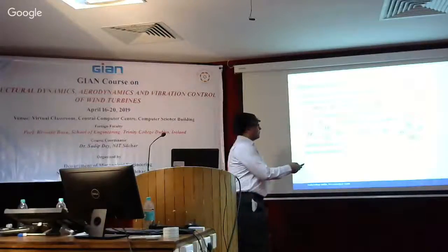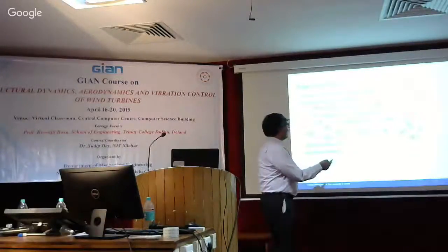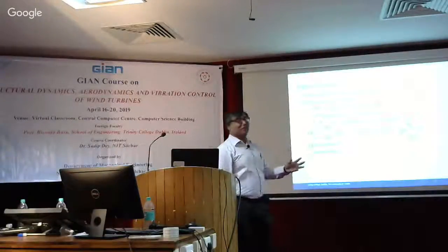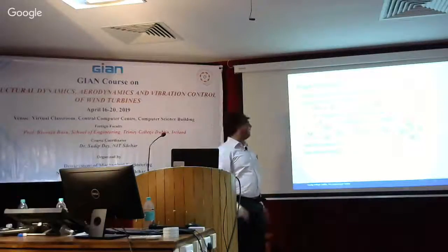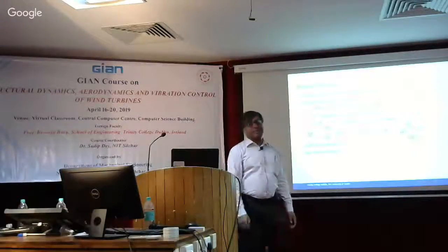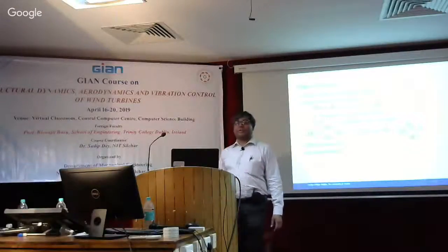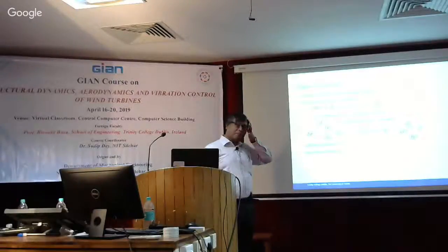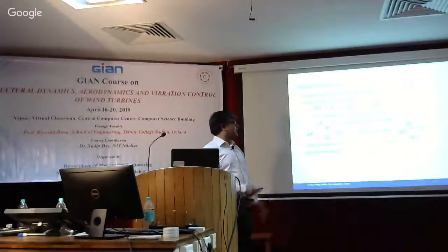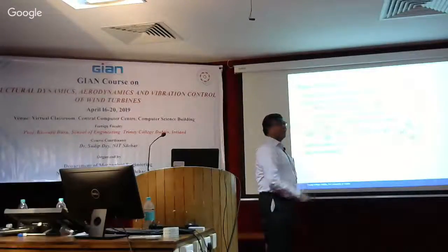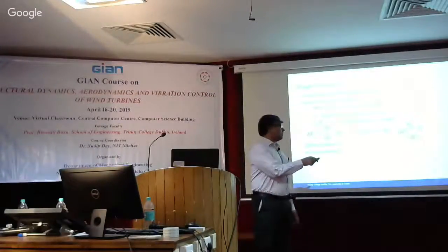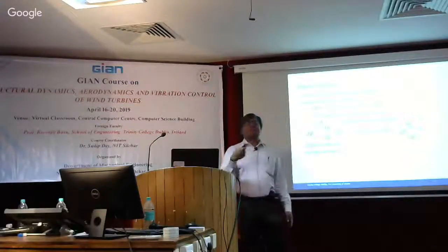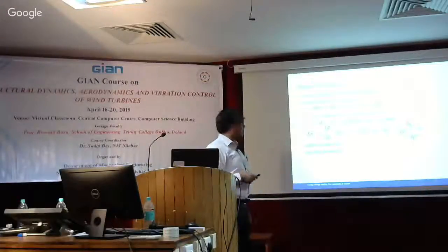So now with this phase difference, if we go from plus to minus, we now actually have taken out some damping from the system. So anyway, it was 0, now you're actually adding a value which is negative damping. That might destabilize the system. And this is a problem because we consider it's a problem also with time delay. Because by the time you measure and compute the feedback, obviously the velocity on the left hand side and the right hand side they are not the same. Because you have measured the velocity at time step t, by the time you apply, the velocity is actually at time step t plus 1. So you need to account for that as well.